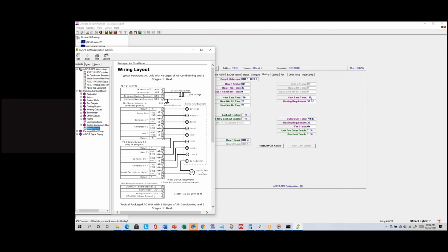Heat-based timer counts to 116, counts to 120, starts back at 0. The heat should then turn on. And based on the heating requirement, it wants to be on for 44 seconds. And we're going to enforce the minimum on time of 20. So that shouldn't matter because it'll stay on for at least 44. So then it turned back on, and then we should be able to see a transition off here. The heating requirement doesn't ramp too quickly.